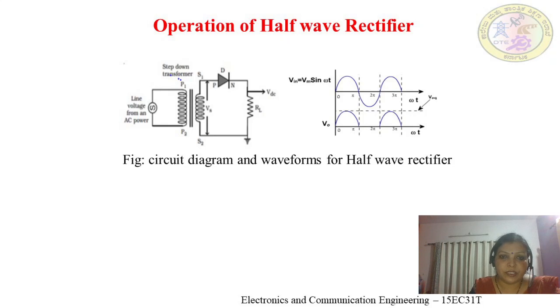Hence, with S1 negative and S2 positive, the PN junction diode gets into the reverse bias condition. In a reverse bias condition, due to the increase in the depletion region of the PN junction diode, the diode is not able to conduct the current.